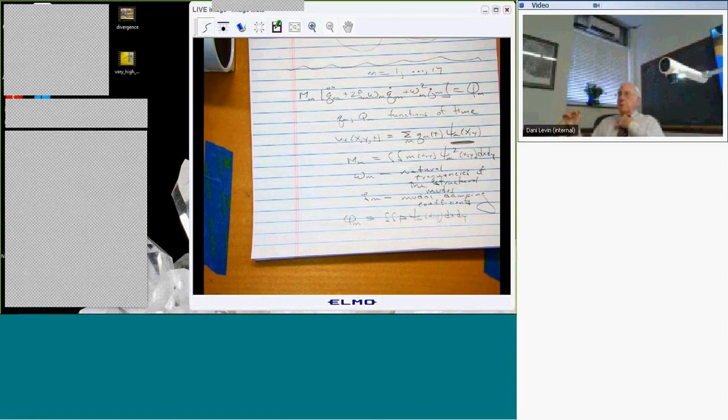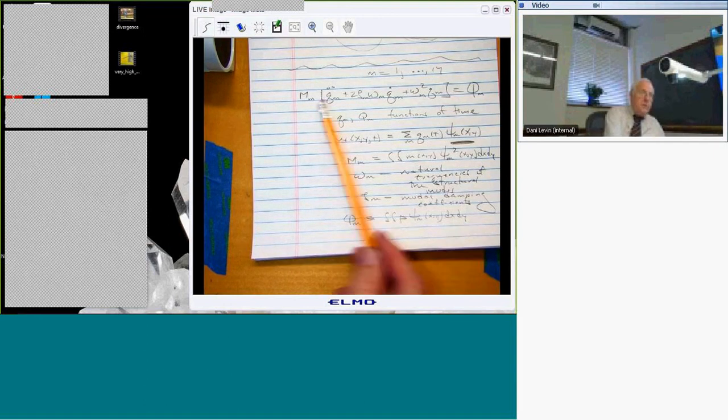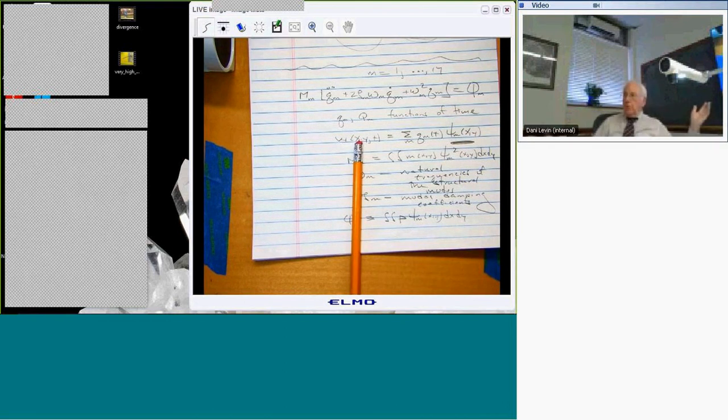Often in preliminary design work, you might have less than 10 modes, since you don't know enough about the airplane yet to justify using 100. But as the design moves along and the test program moves along, and you have a better and better definition of the structure, you try to find more and more modes. But the point is that these equations, even though there may be a lot of them now, look just like the one we dealt with before. And all those things we said about the particular example today apply.